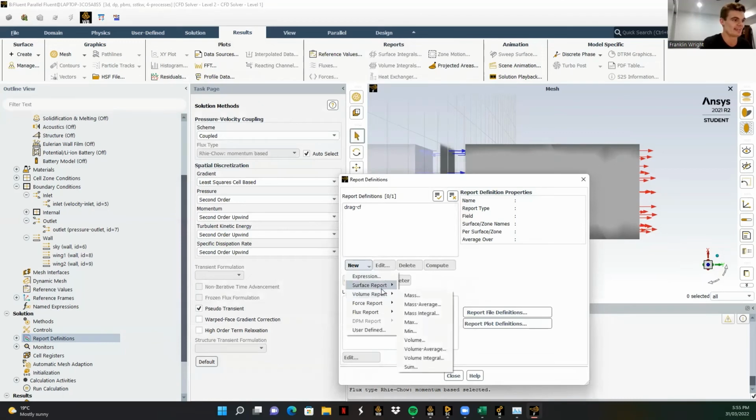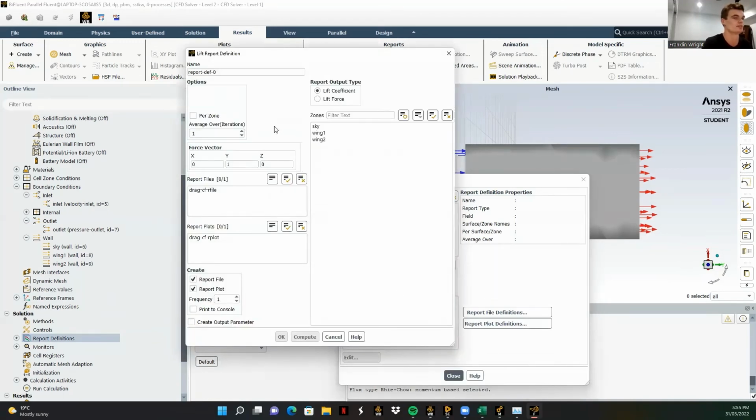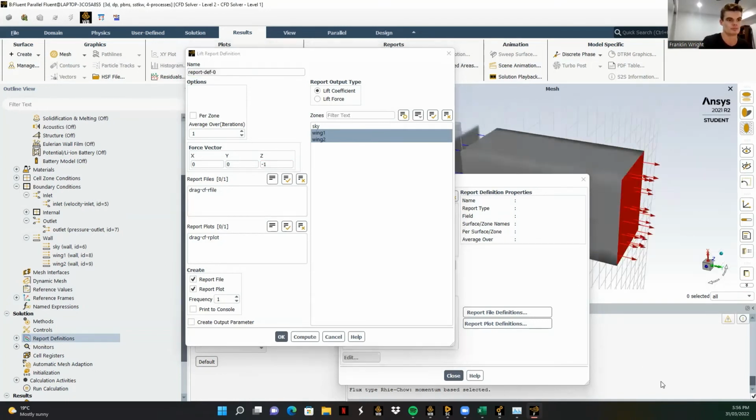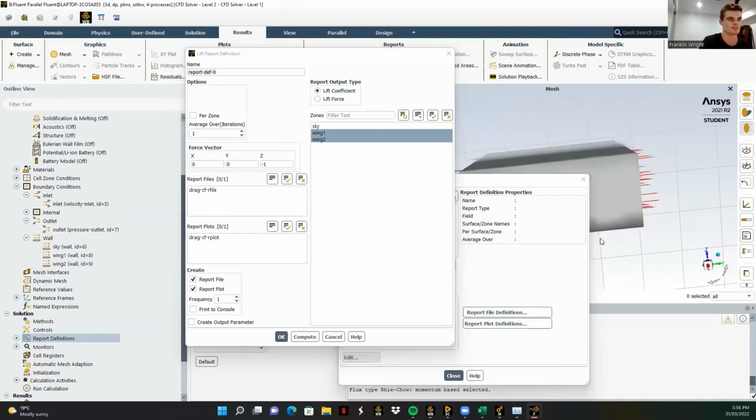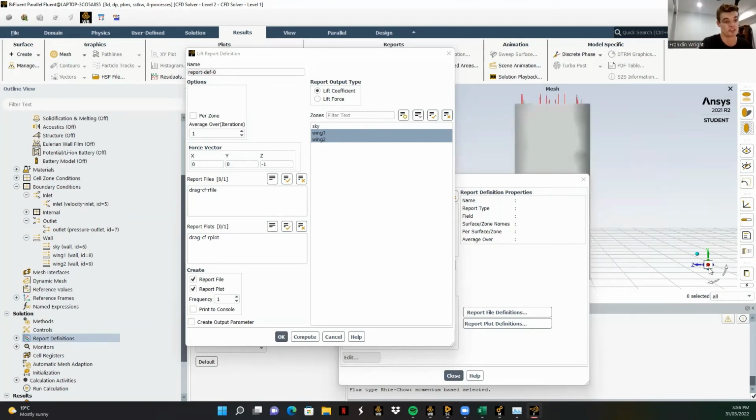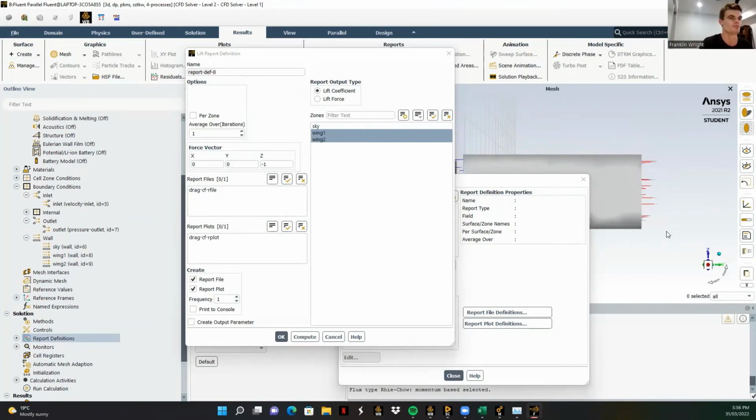We're also going to create one for downforce. So this one you've got to lift, because obviously lift is opposite downforce. Our downforce will be acting in the negative z direction. Yeah, negative z direction, like that. If you're unsure, just check. Your model may be different to mine with how the cardinal direction is set up. Make sure you double check that. Coefficient, and create output parameter.